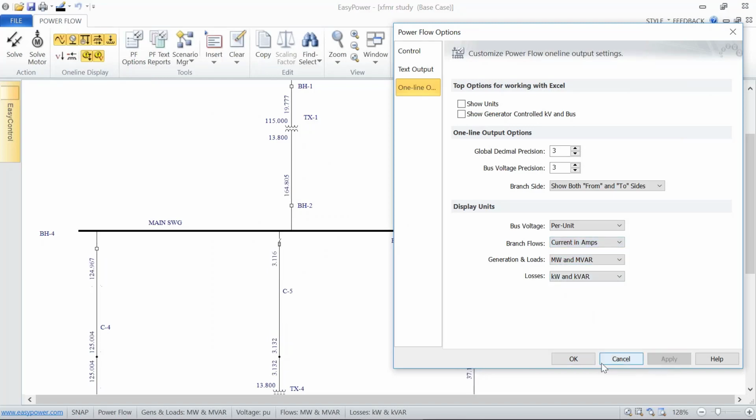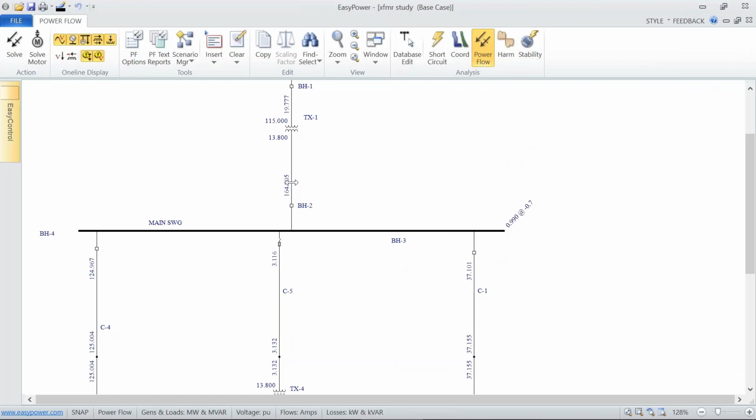A typical current for this system is 165 amps. So we don't have to come anywhere near 9,000 amps to protect this circuit. Anything over even say 10 times this value is perfectly adequate in terms of fault protection.